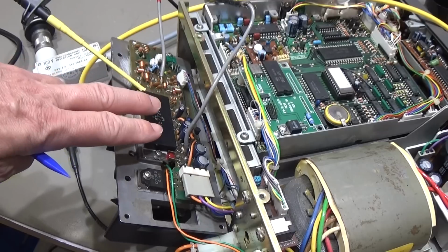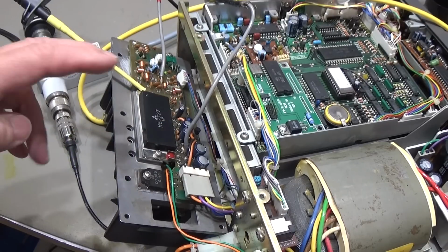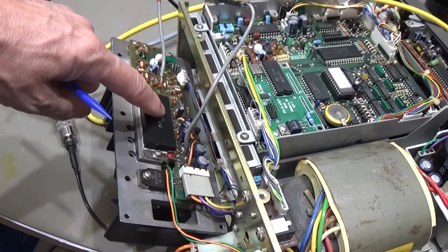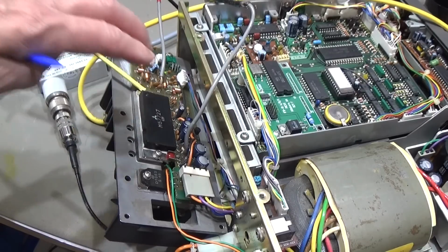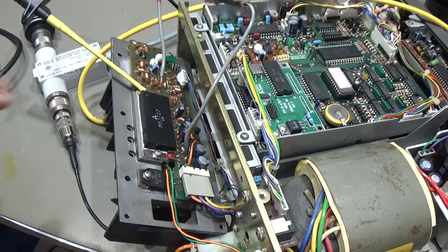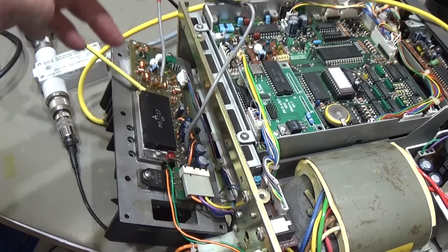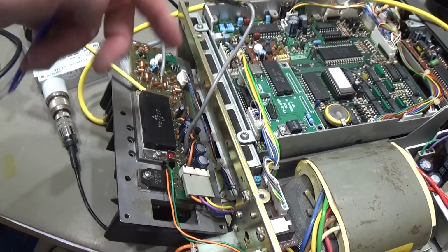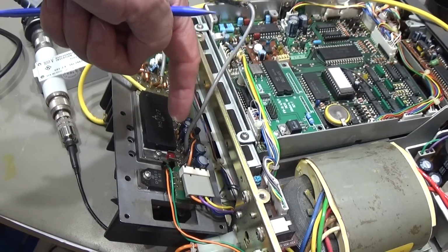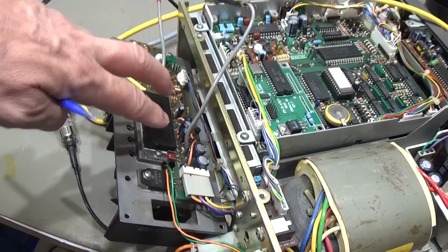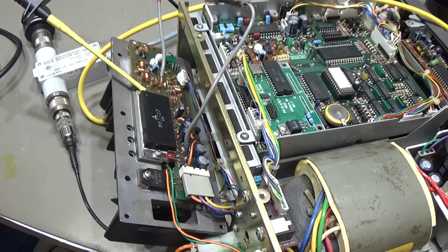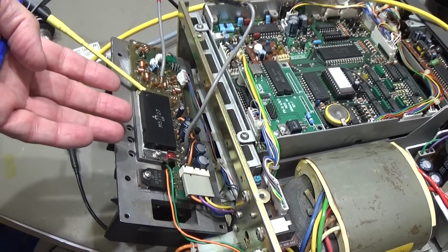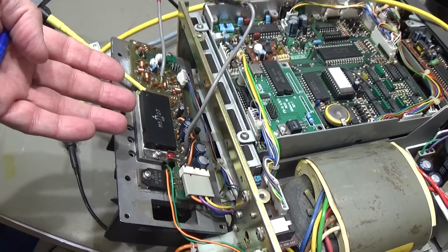And well, what I can say already is that all the voltages which need to be present here at our final stage are fine, but when we feed here an external signal into our power amplifier, we do not get an output, and that is exactly what I was expecting.